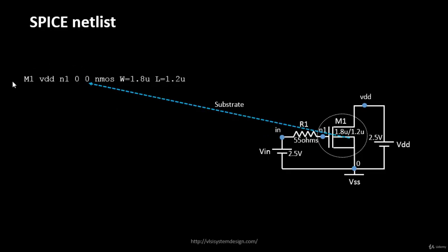So the fashion in which this is written is, you give the MOSFET name, you give the drain, the gate, source, and substrate. It's DGSS: drain, gate, source, and substrate. This is the order in which it expects the pins to be. This is basically the pin ordering.